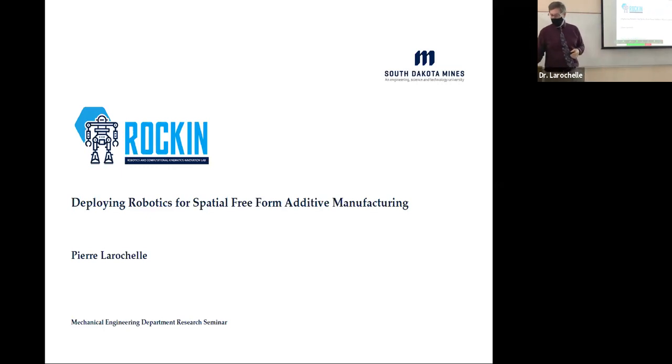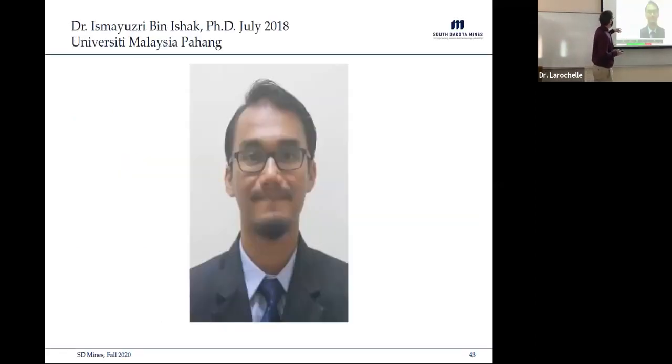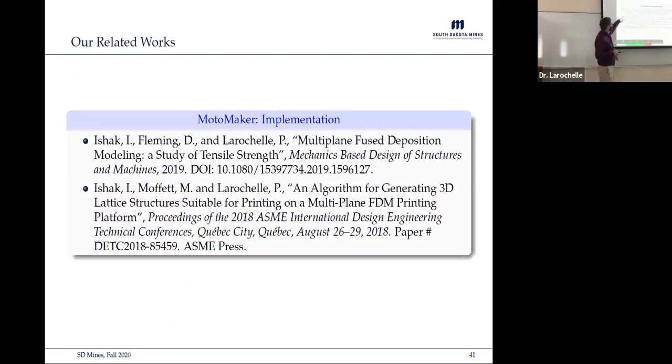For example, on material properties, I already mentioned we were very excited about the results that you'll find in here. Our dog bone specimens had yield strengths 2.5 times what's coming out of a traditional 2.5D printer. If I'm going to do a tensile test and I want to maximize the tensile strength of this dog bone, which directions do you want to put the material in? You definitely don't want the dog bone to be sliced like this.